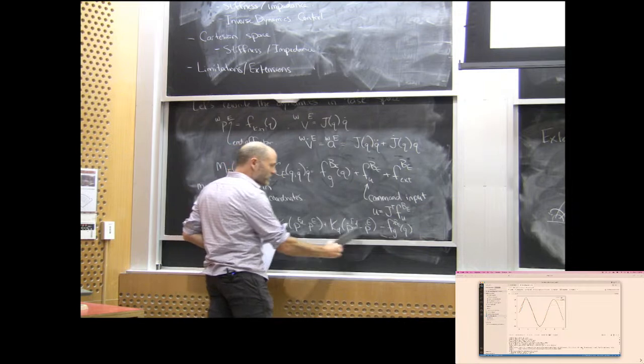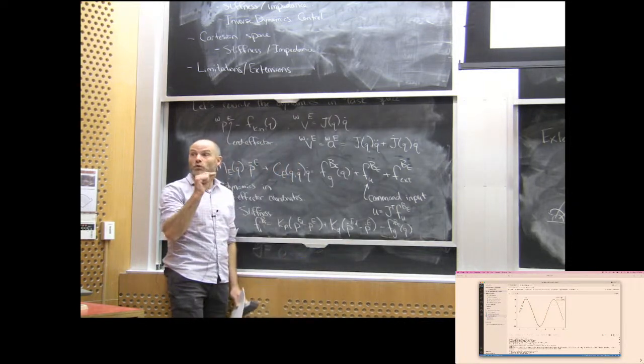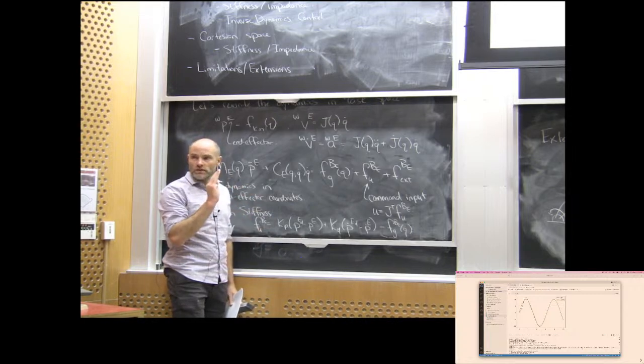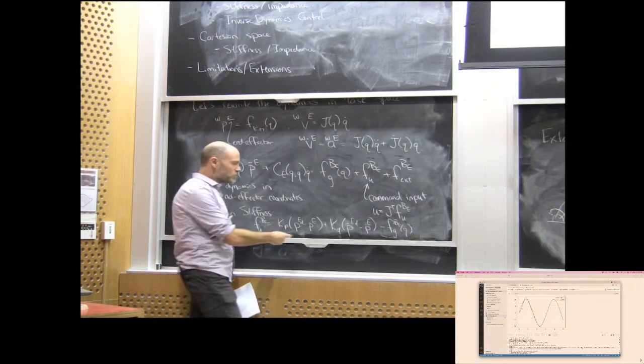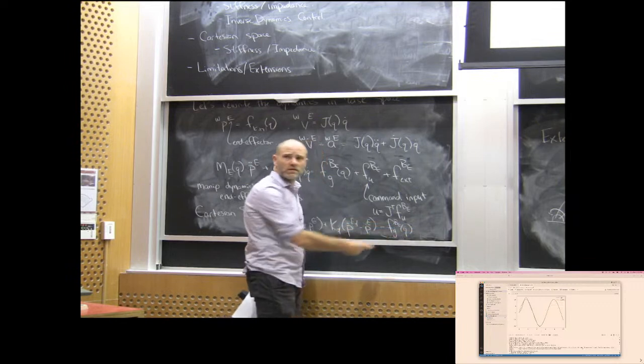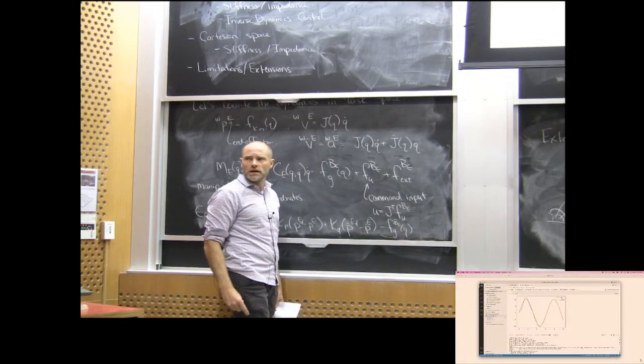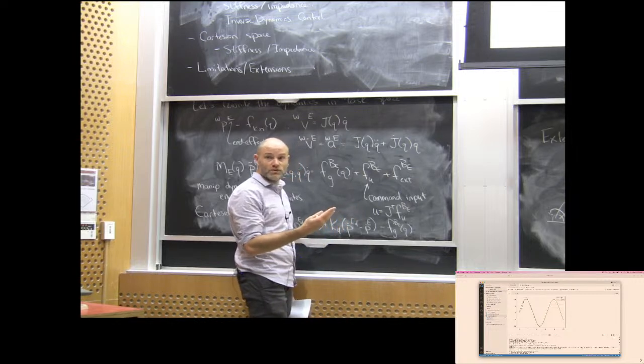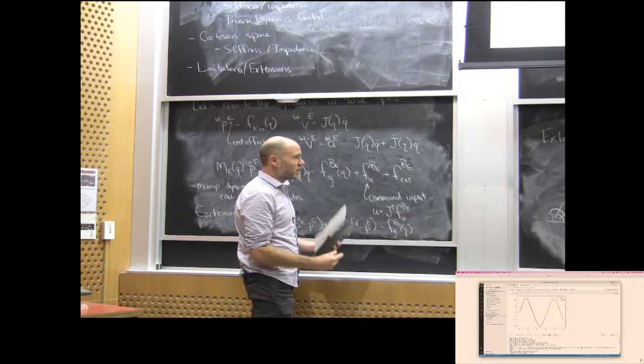EWA will actually also accept a feed-forward force. We normally live in joint space, so I know better what it does there. I assume it could also take a feed-forward force in Cartesian, but I'd have to look to make sure. We almost always use joint space control for a limitation I'll talk about in just a second.